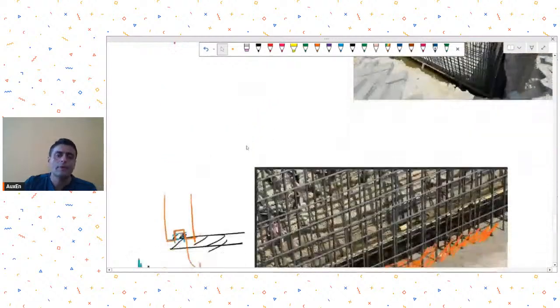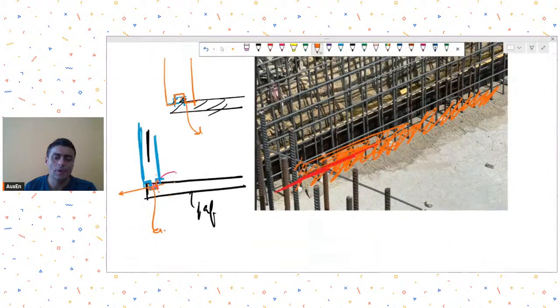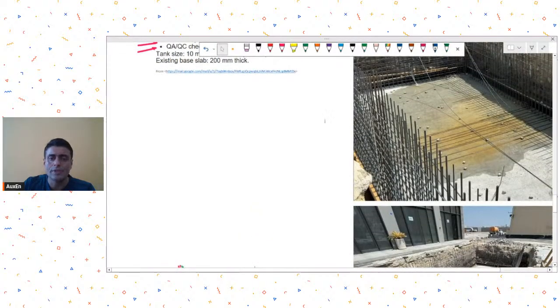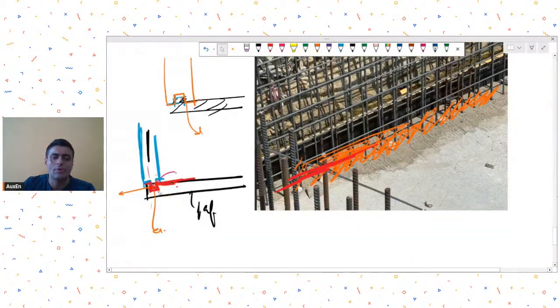So, as I told you, water stopper, because the existing thing does not have any water stopper. If you are able to drill, I don't see the space available to have a drill like this. If you are able to drill, a water stopper here would also be ideal. But the next best thing would be to create an excavation, a small little depression in the raft over here by taking out concrete from here and then doing the casting. I don't see that you will be able to provide a water stopper over here. So instead you may try to have this type of a protrusion.